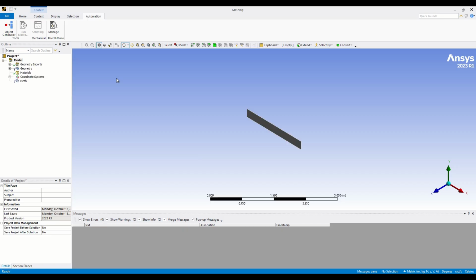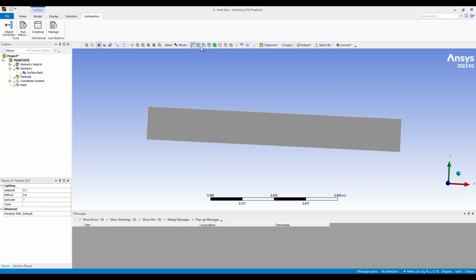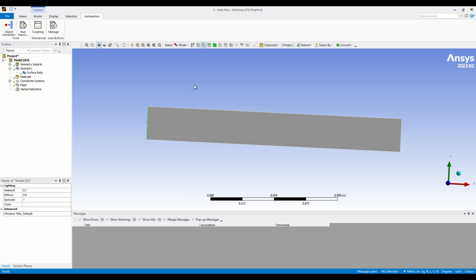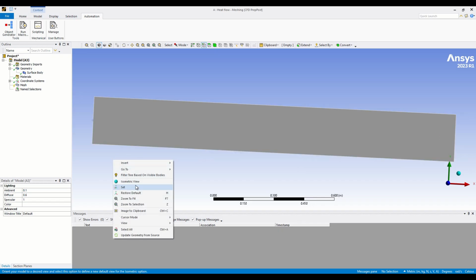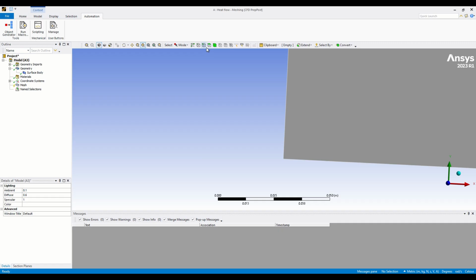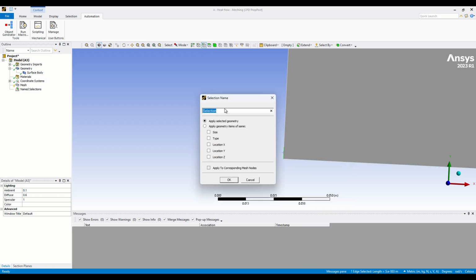In this meshing process, we first have to give the name selections and then do the meshing. You can see the structure. First we will give the name selection. From the left side we give air inlet, and then the bottom is split. You can see in the geometry that we have split it there. In the bottom, a small line needs to be drawn. I click on the geometry and type the selection name fuel inlet.